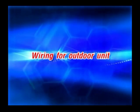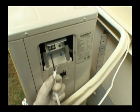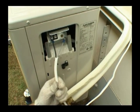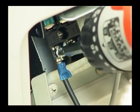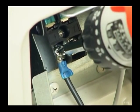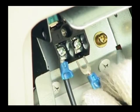Wiring for the outdoor unit. It starts with connecting the wires from the indoor unit to the outdoor unit. The wires can be lined with a refrigerant pipe and then connected to the terminal block. Match the terminal block numbers of the indoor and the outdoor units.